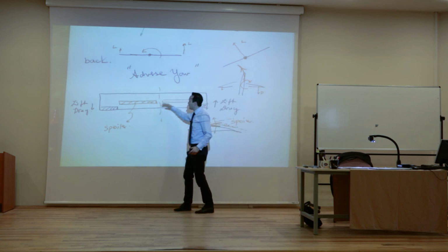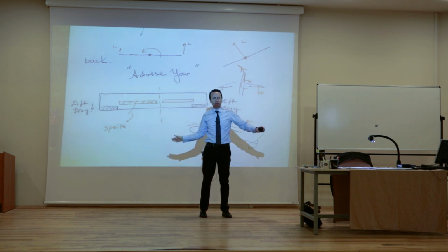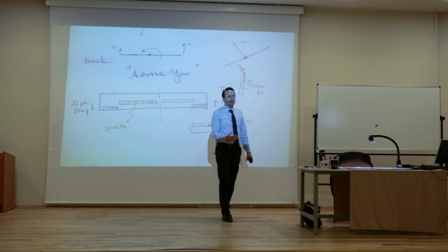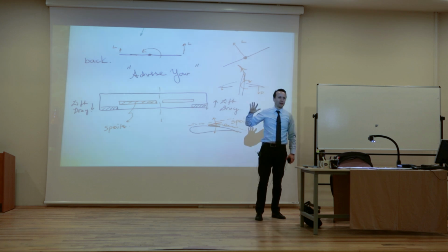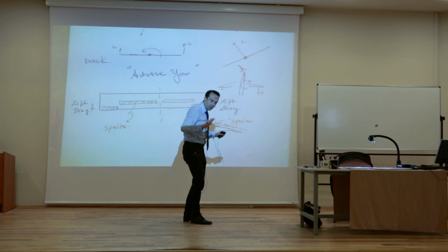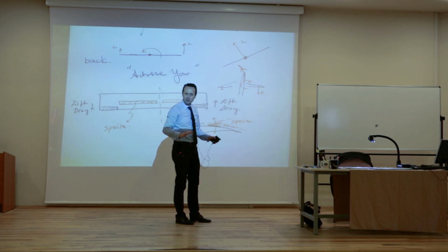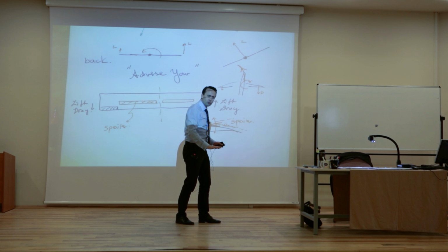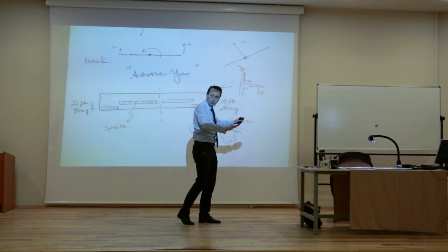You might have seen on airplanes these little things that sometimes go up and down, the spoilers. Sometimes it's because of that adverse yaw, and sometimes you can even adjust the heading with it, right? A little less lift and drag and all this. Especially, the spoilers are very useful when you land. So what do you want when you land? The worst thing is, when you land, after you put the landing gear to the ground, you don't want the aircraft to lift again because you are getting into a real dangerous situation. You are very close to the ground. And if you do things wrong and you lift again and you roll, you really don't have much margin to move when you're up in the air again, right? Because you are so close to the ground.